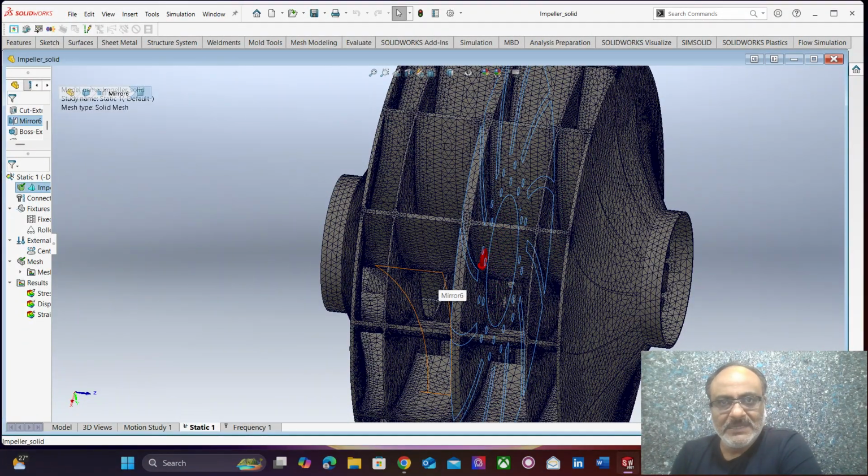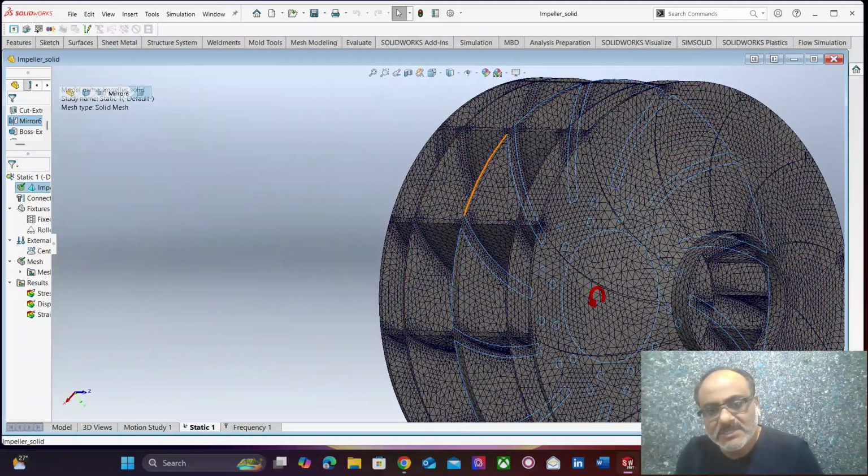We did that just because we wanted to stiffen that particular region, because we know that the stiffness keeps reducing towards the edges and the stiffness becomes more towards the center. So that is the reason the probability for any circular membrane or structure to fail at the edges is more than to fail at the center. Which means the cracks generate from the outermost edges, and they propagate inside and go to the center.